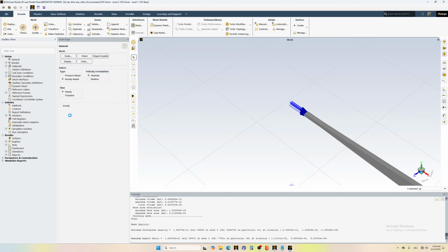Okay, density based, and we will use a steady case, not transient, because it's faster if you are using steady. Transient takes a much longer time and much more computing power. Probably in the future I will show you an example. Right now we will use just steady, which is enough to get the density profile required in our experiments, or more specifically in plasma based wake field accelerators.